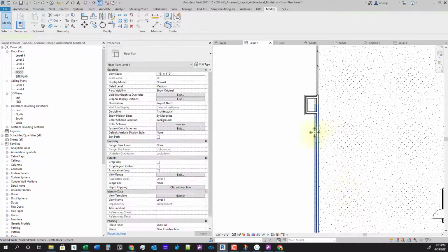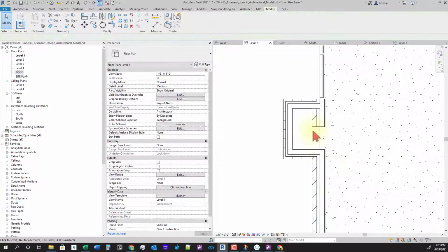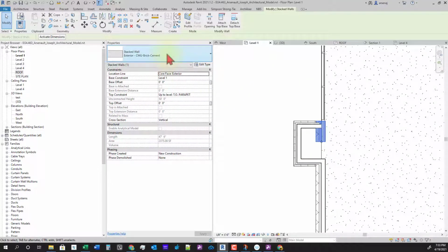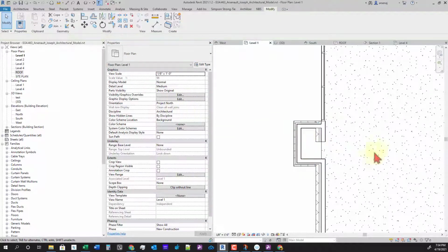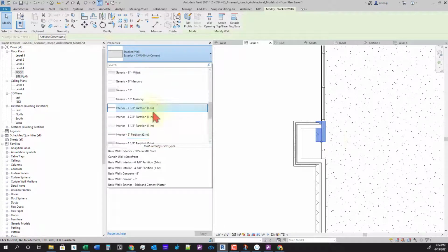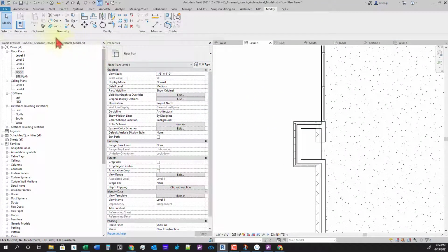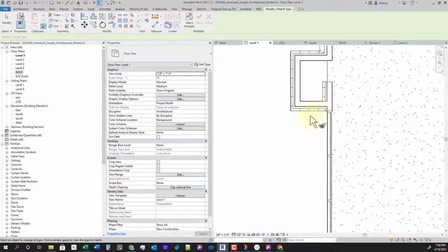Undo because I don't like that warning. We'll just drag. And we can change this wall to the same wall as this. And actually, if you want, you can come up here to the clipboard. Next to where it says clipboard, you can match properties or type MA. Tab in to select that wall, and then select that wall, and it'll make it the right wall.